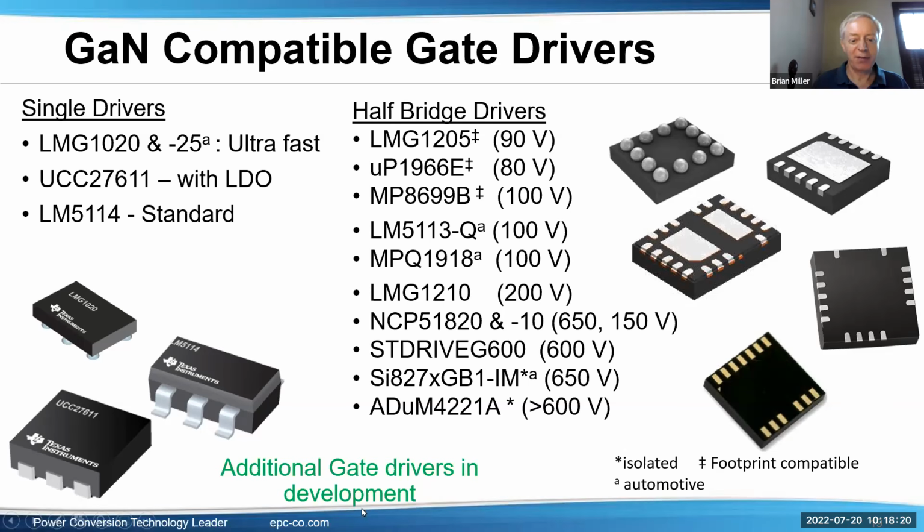There are additional gate drivers in development. There are also GaN controllers, power supply controllers in development, and there are 3 that have been released. 2 from Renesas, ISL81806 and 807, which are dual buck and also dual boost. And so far, Analog Devices has released one advanced buck controller, which has a native GaN driver in it, which is LTC7891. And again, there are more drivers and controllers coming.